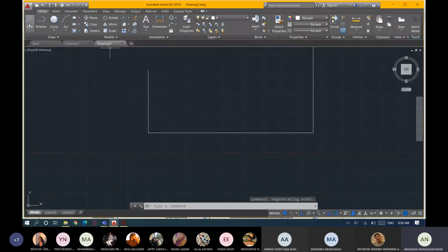Pick a line or a polyline, come here and move a little bit to that direction. Do not press enter. Move a little bit to that direction. And as I told you, with the help of object snap tracking, now I will be able to identify that 40 millimeter away from this starting point, whether it is in this direction or in that direction.